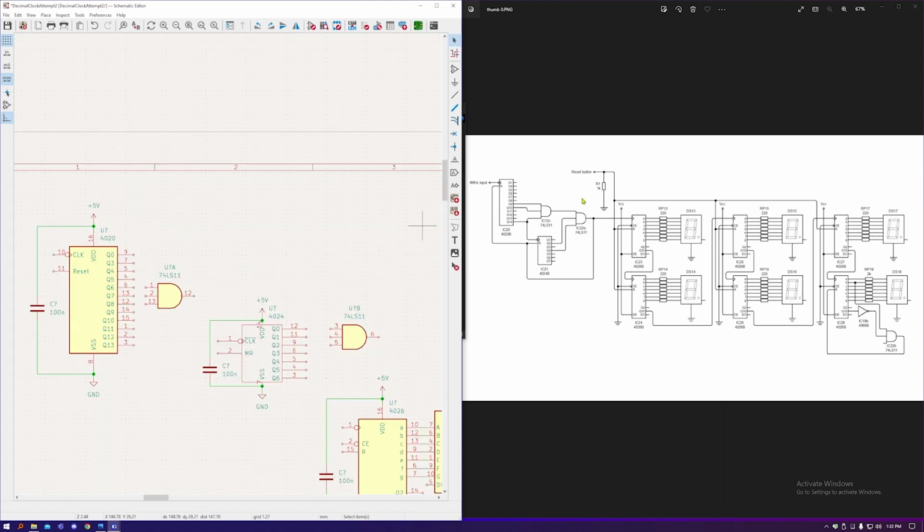So all I'm going to do for this is copy the schematic that we made last time. One difference you might notice is that the outputs on these two chips start from Q0, whereas on the software we did last time, they numbered them starting from Q1. That doesn't really matter, just take one off the pin on this one to match with the pin on this.